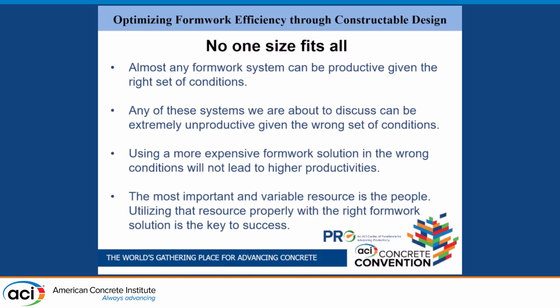As we look at these formwork systems, I want to stress that not one size fits all. Almost any formwork system can be productive given the right set of conditions. You make something 8 foot high, very thin slab that's continuous. You can run down to the lumber yard and grab 4x4s and 4x6s. It's going to be productive. There's just nothing stopping it. It's easy. However, any of these systems that we're talking about can be extremely unproductive if given the wrong conditions